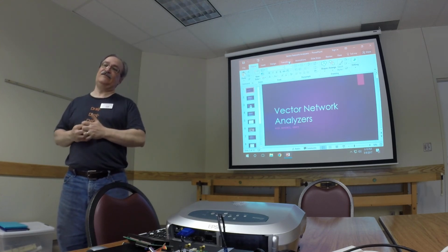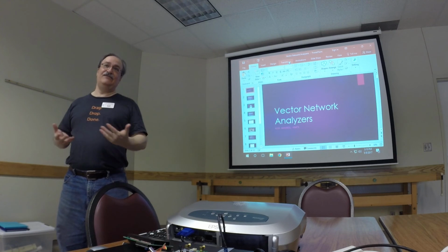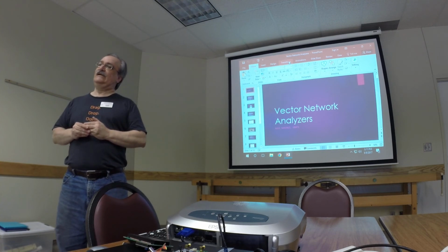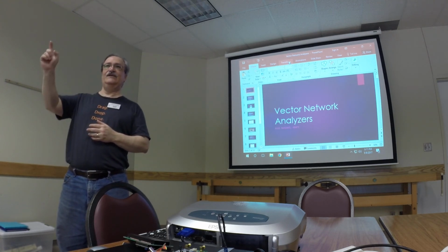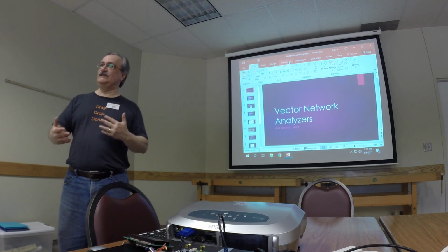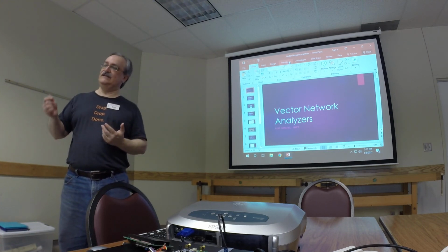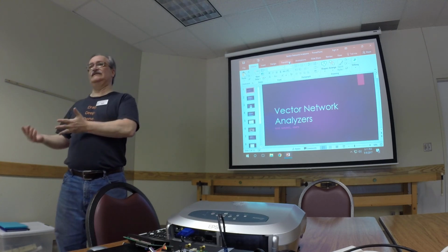It's high quality stuff. It will take 5 kilowatts, don't care, but it's heavy. It's got heavy duty current balun in it. 2-core balun instead of single-core balun. Some of the theories on Windom and why people like them, as you may know, it started out being a random wire-fed antenna, and people have looked at it in terms of launching, which is a term you typically associate with traveling wave antennas, but essentially kind of a crack-the-whip effect because it has a very high voltage and impedance on one end and a reasonable impedance on the other end.